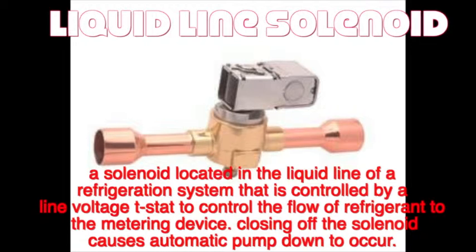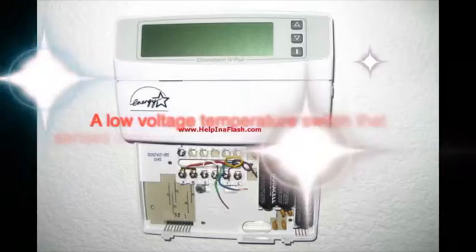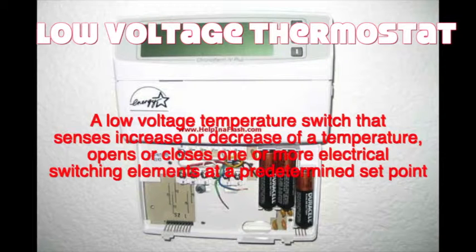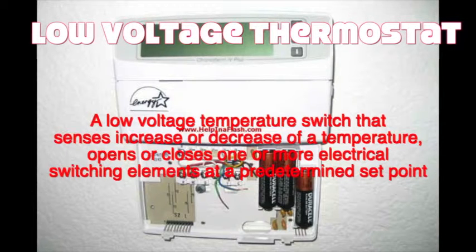That's a liquid line solenoid. Low voltage thermostat: a low voltage temperature switch that senses increase or decrease in the temperature and opens or closes one or more electrical switching elements to a predetermined set point. That's a low voltage thermostat.